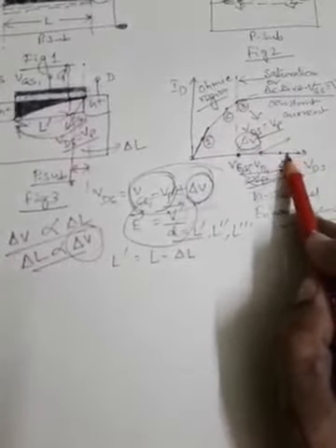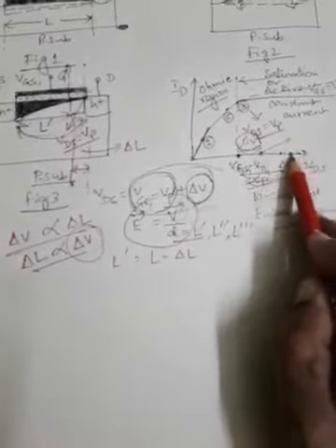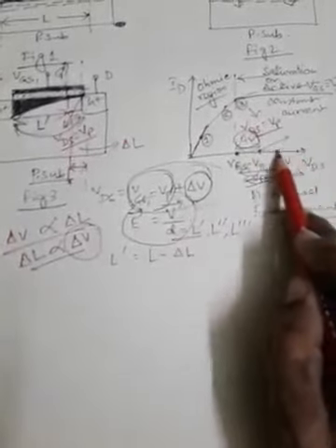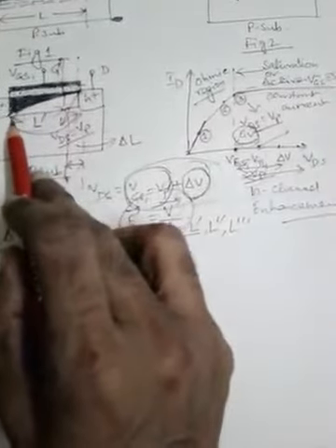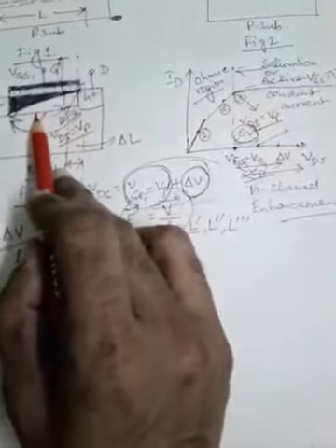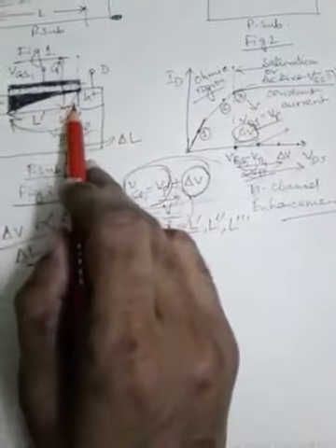So if we now again reduce the delta V value, that means if we come back to a lesser value of VDS, moving towards the pinch off voltage point, or moving towards the left side along this voltage axis, what will we be seeing? We will be seeing that the length of the channel, without decreasing, will now increase further.